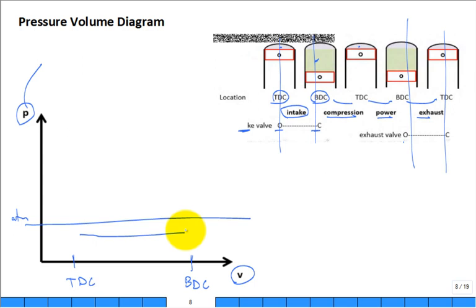But they would have vacuum used for a lot of things inside your car. Anything else that I'm forgetting? The booster on your brake is vacuum. Timing advance on older ones, right? That would be a vacuum on your distributor, timing advance.